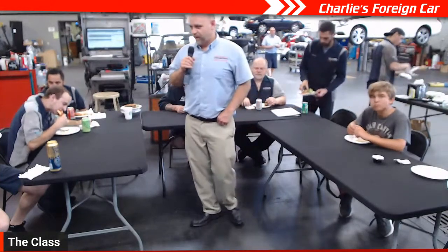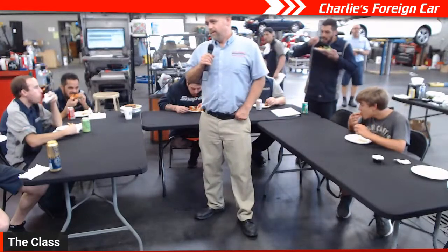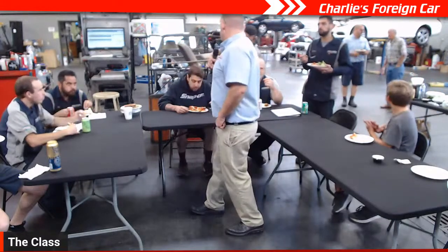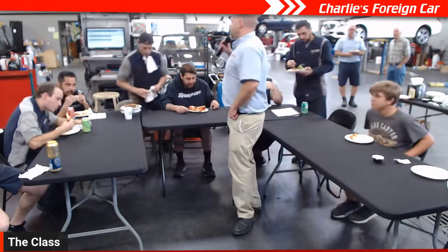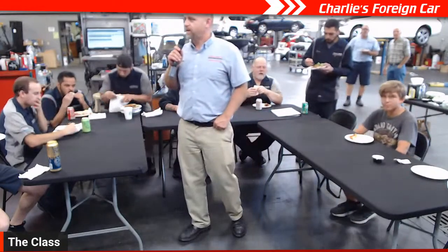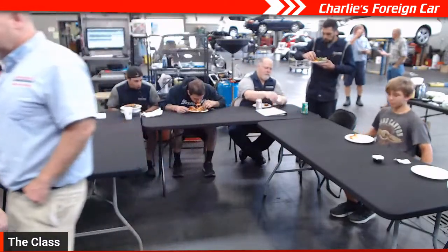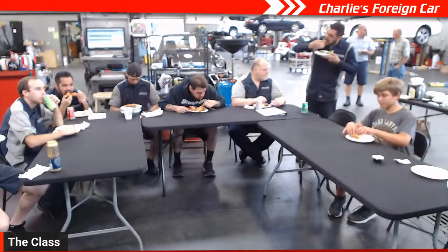Anyways, we put a new one in, and we still have our same code, P0014, which is, Gianni, do you know what the code definition is? Exhaust cam over advanced. So then we've got a whole bunch of test equipment hooked up to this car right now, and we are watching.